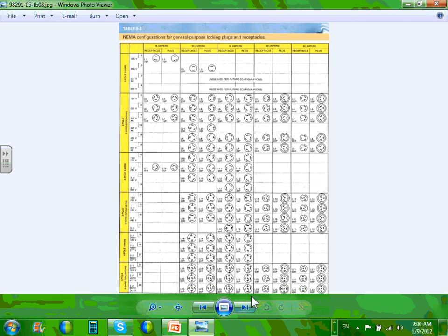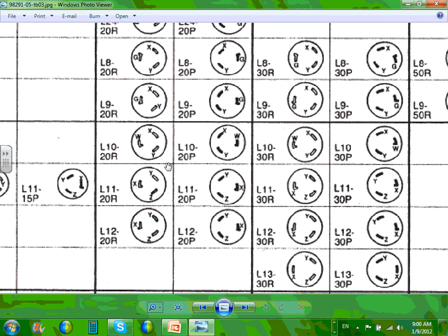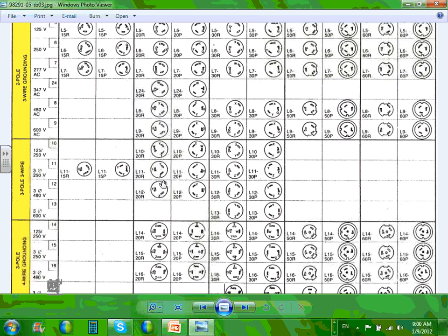Is the phase wiring critical on these, on the installation? Yes, to make sure you have phase A, phase B, phase C, or X, Y, Z. Otherwise, in a three-phase system, you know what happens: instead of exhausting the air out, you start bringing air in. You're reversing a motor. Polarity, they call it polarity, is very important.